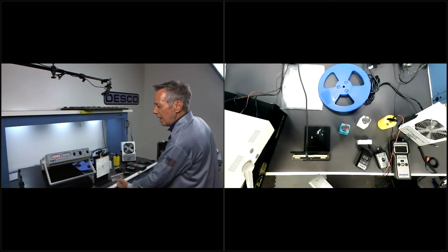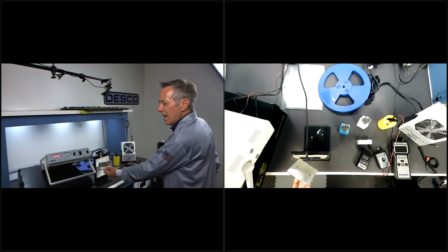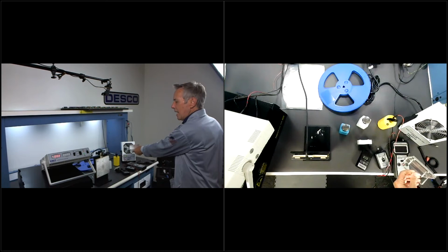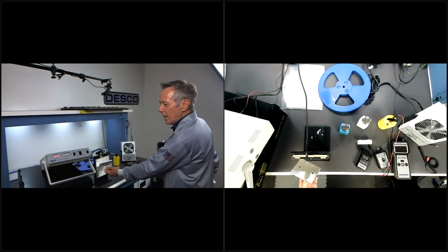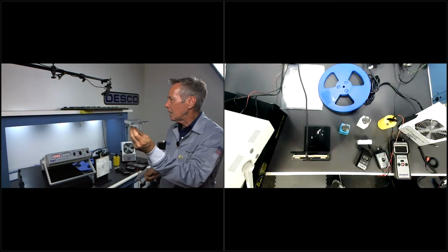It's the same thing with conductors. If I'm not grounding this conductor, it can also hold a charge. So I can show you real quick how I put that charge on it, but now I'm going to hold that conductor in the presence of the ionizer. And again, I've knocked that. Oh, I got to zero my plate. Hang on one second. Let me do that again. So I'm going to charge this back up. I'm going to hold it in the presence of the ionizer. And I'm going to bring this back over here. And you can see that ionizer knocked that charge off. So one of the great things about ionizers, or a couple of things, is one, they help keep things from becoming charged up, but they remove charges on insulators and they remove charges on conductors.